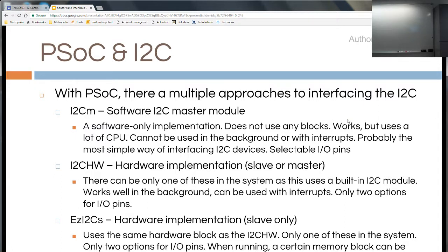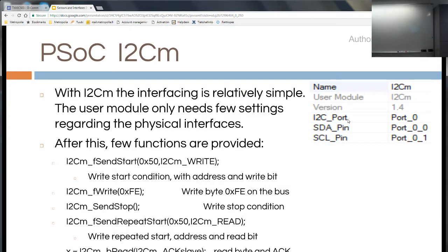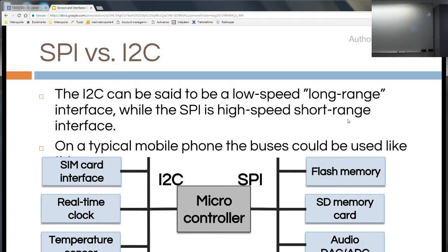You can plug in a signal, convert it in a PSOC, and then just have the easy I2C slave interface, so that you can actually go on a Raspberry and read the I2C bus from that address to get the A to D conversion signal. Very simple way to add AD. It's just a few wires. Okay, and then some things that we actually go through on next week's tutorial.